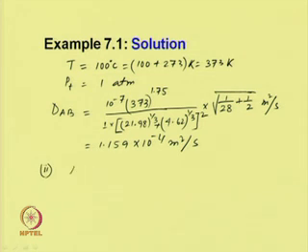That is at 2 atmosphere and 100 degree centigrade temperature. So, for this case, since we have already determined for the same system the diffusivity at a particular temperature and pressure, there is no need to calculate the diffusion coefficient for the same system at different conditions from scratch.